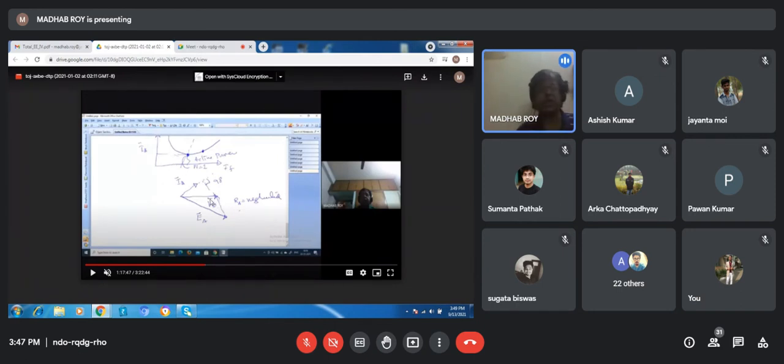So that is established. Similar things will happen on the left hand side if it is under excitation. Under excitation means this length will be very small. Suppose this is half the length of EA. Then jXs IA will be along this direction, and you can see the direction of EA. EA will come down here because it will always be at 90 degrees. So a lagging power factor will appear. This is basically called a synchronous condenser.